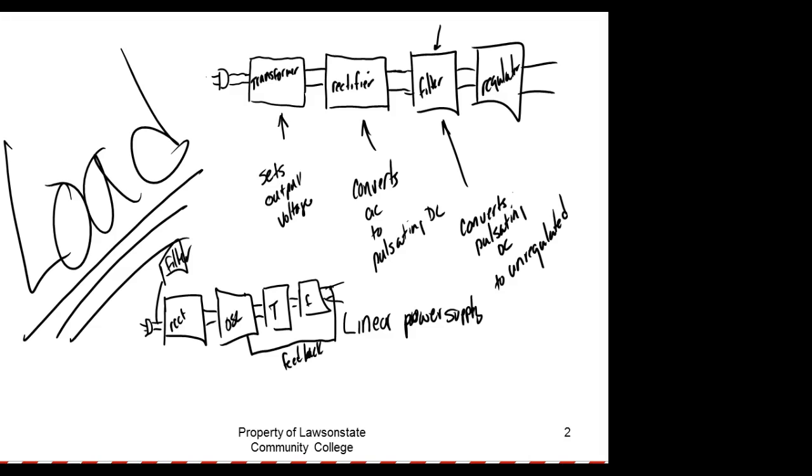So these guys are hard to troubleshoot. Normally these are consumables. So right now, if this thing goes out, what am I going to do? I'm not going to try to fix it. I'm going to throw it away. But if the power supply goes out in the trainers, I'm going to fix it. Why? They're a linear power supply, and they're easy to fix. They're not extremely difficult once you get a little troubleshooting under your belt. We're going to look at that in a minute.